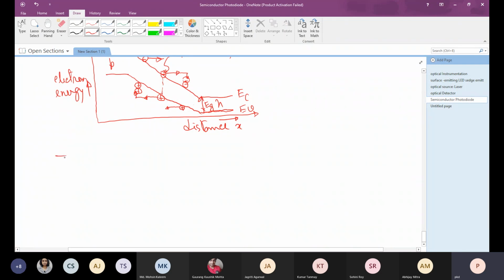Generally, the ability of the electrons and holes to impact ionize is related to the reverse bias potential as well as the band gap energy. However, the ability of impact ionization is characterized by two ionization factors corresponding to the electrons and holes.